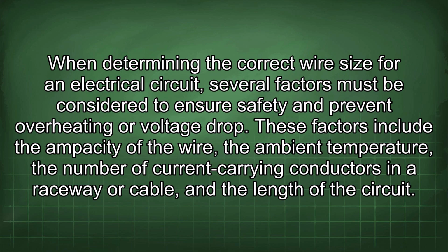When determining the correct wire size for an electrical circuit, several factors must be considered to ensure safety and prevent overheating or voltage drop. These factors include the ampacity of the wire, the ambient temperature, the number of current-carrying conductors in a raceway or cable, and the length of the circuit.